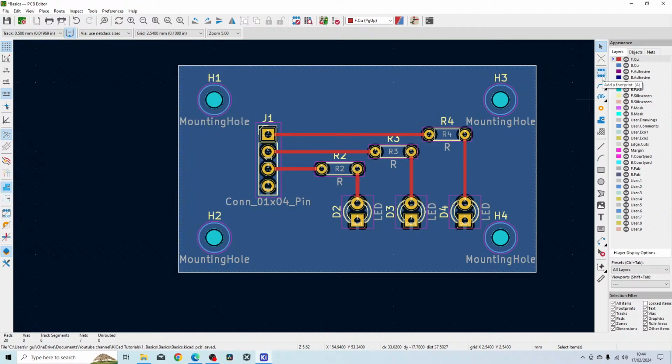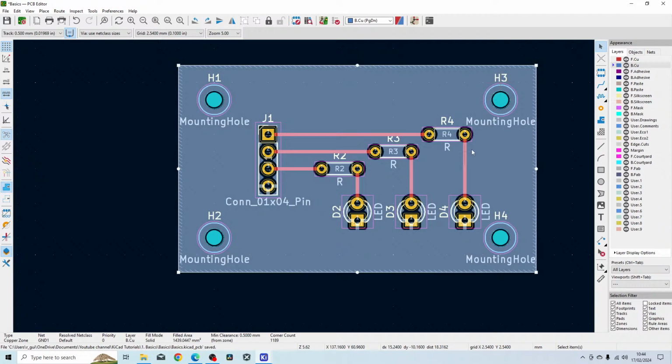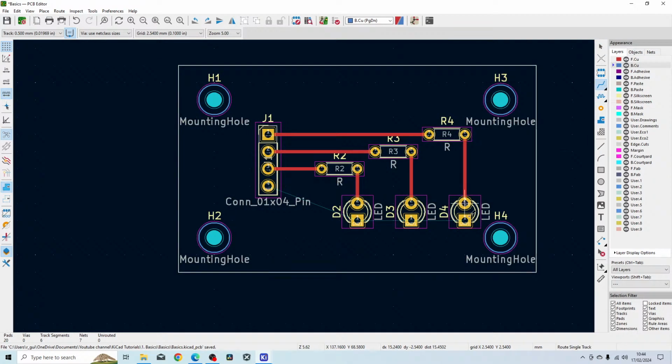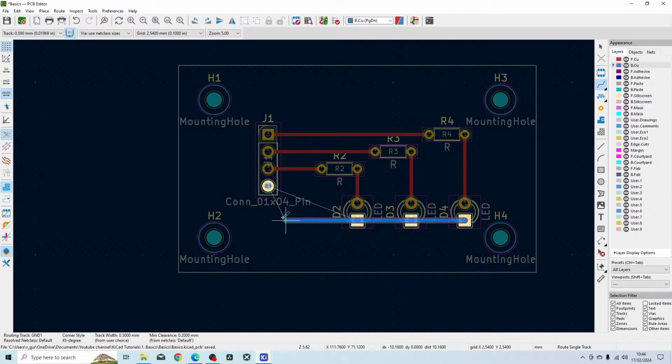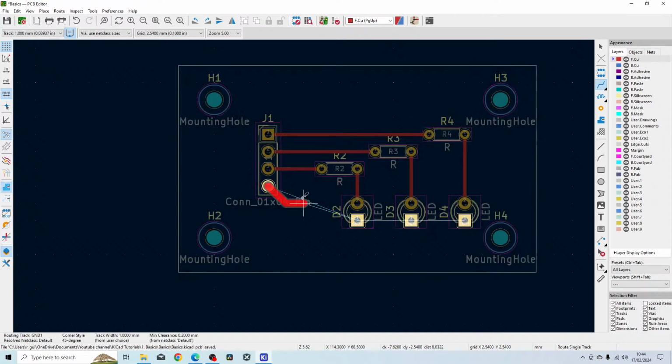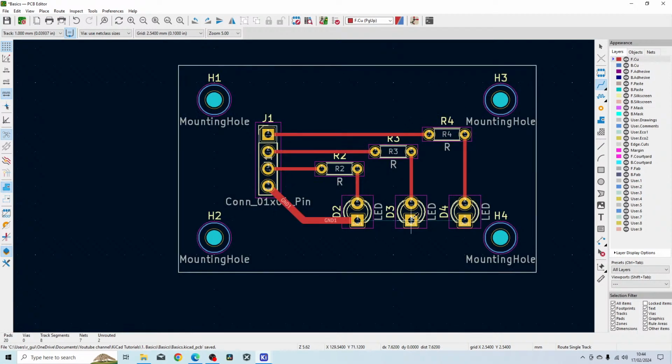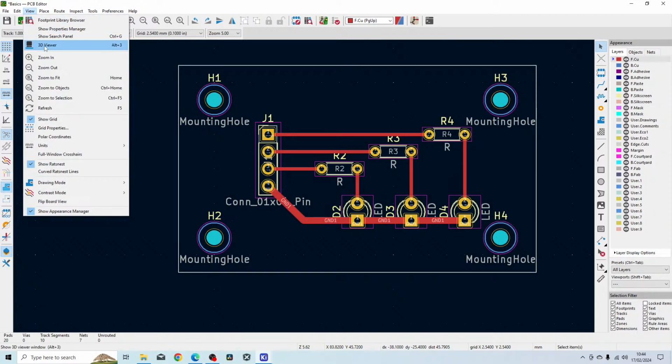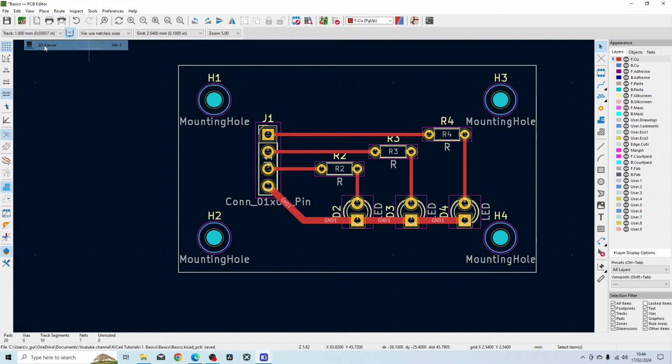Two layer boards can be a bit more expensive than normal boards sometimes. I'm not sure anymore, maybe because PCB boards have just gone so much cheaper lately. But because it's such a simple design, we can use a single layer board. So I'm just going to remove the ground plane and replace that with a track. Let's see what that looks like on our 3D viewer.